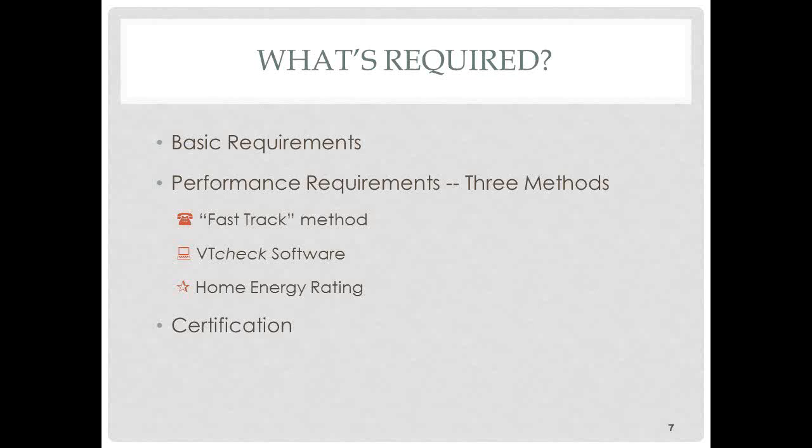describe the entire thermal envelope of the building. So the entire layer that separates inside from outside will be described in the software. For each piece of the building, you'll be entering an area in square feet and an efficiency measurement of some sort, which is the R values for walls and ceilings and other opaque assemblies, and U values for windows and doors. Those are the 2 do-it-yourself methods.